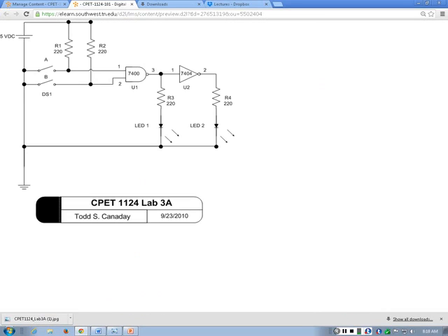What it is telling you is that you will need the 7400. That's the NAND gate, okay? NAND gate, and that's the inverter. And then you see here there is a resistor, I'm saying the resistor 220, and there are two 220s here. So basically, and there will be an LED here. Now, look carefully at what you have here.